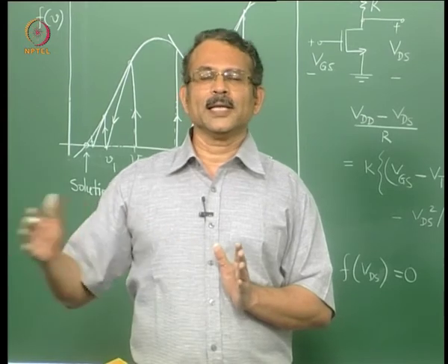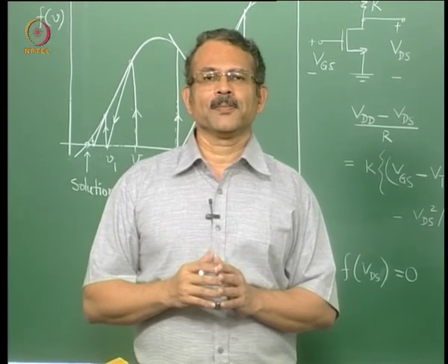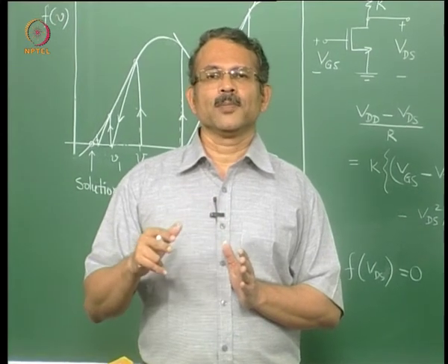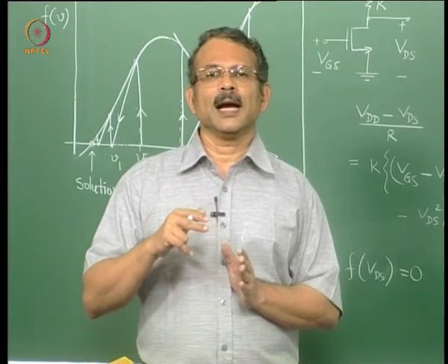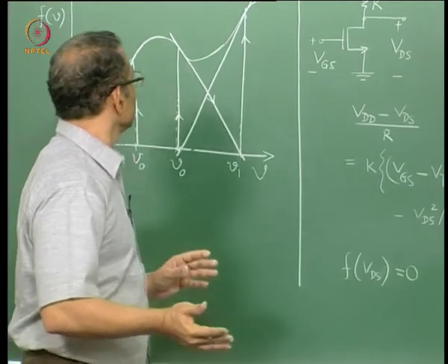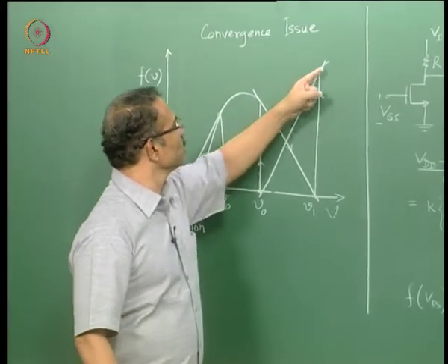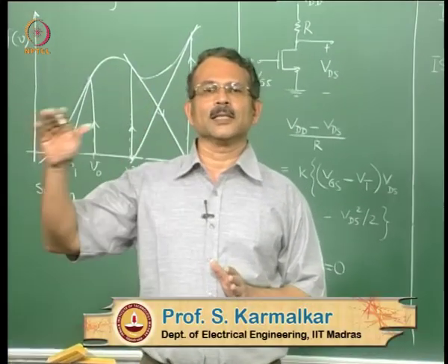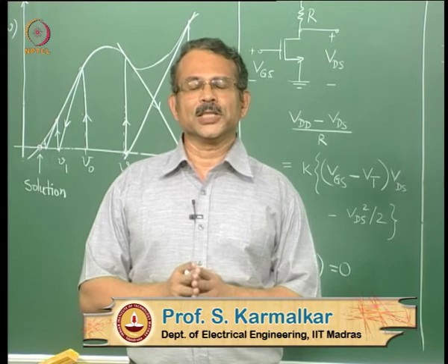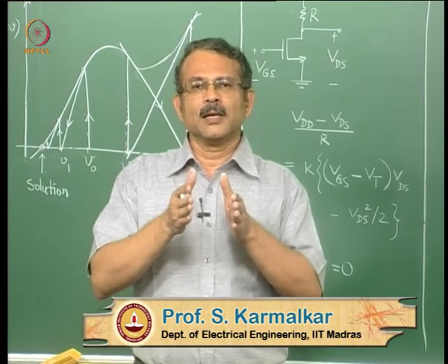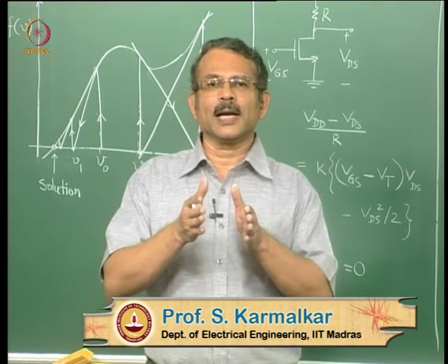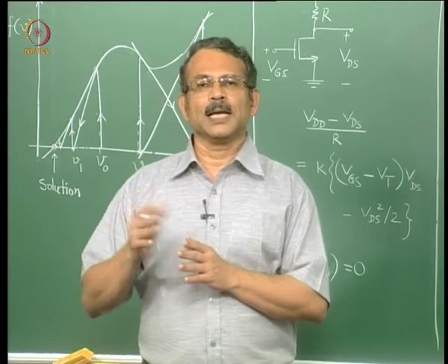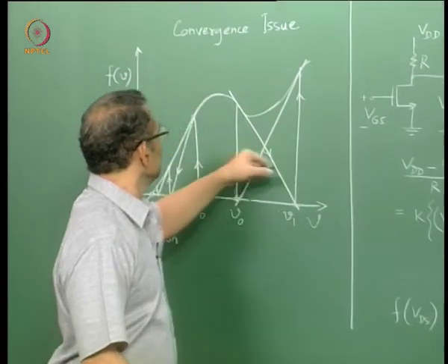So for very large voltages, much beyond the practical range, your current voltage model should not be unrealistic and should not, for example, result in shapes such as shown here. For example, if your model equation gives negative conductance beyond some voltage range, in the range in which the device works it may be alright, but beyond the range it may give negative conductance or other such problems, and they in turn will give rise to this kind of situation.